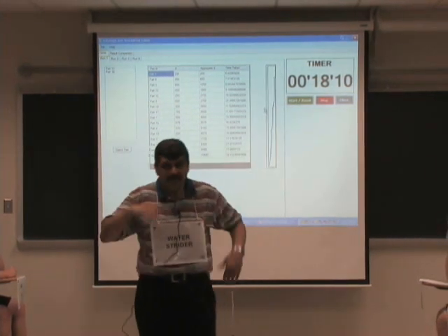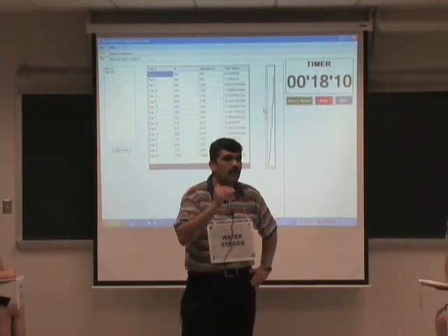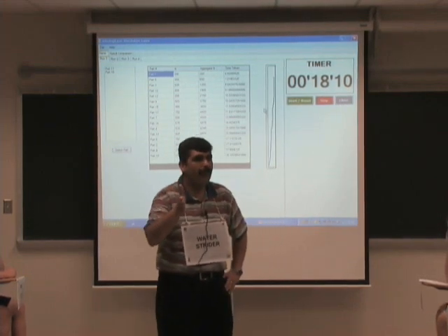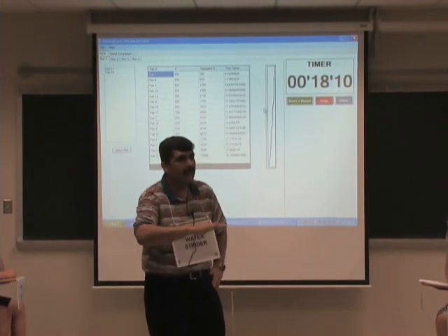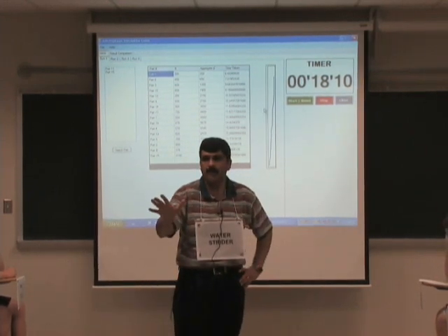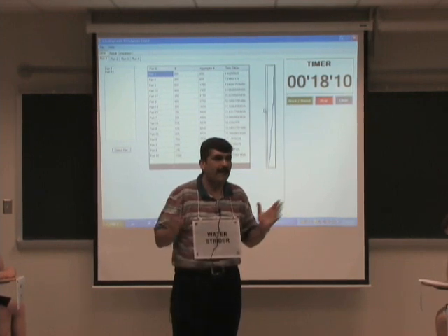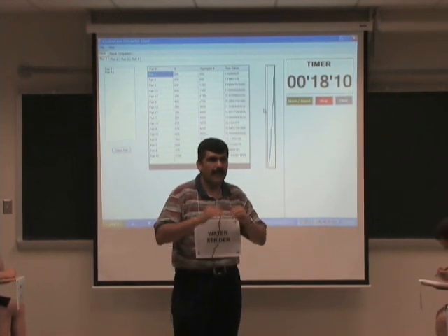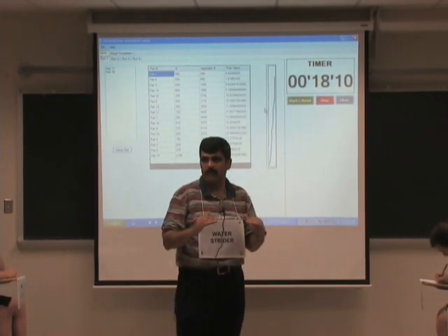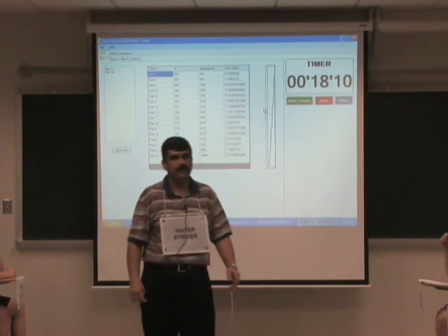But the point is, fundamentally, if you design the layout badly, if you choose the wrong mix of products, wrong sequences of production, you don't balance the workflow, poor handling, no visual communication, no performance metrics, poor cross-training of employees, you essentially have a messy factory, a bad factory. So the layout starts you thinking on all the best practices you can bring to bear. But it's not a solution by itself. There's a lot more that you will have to do.